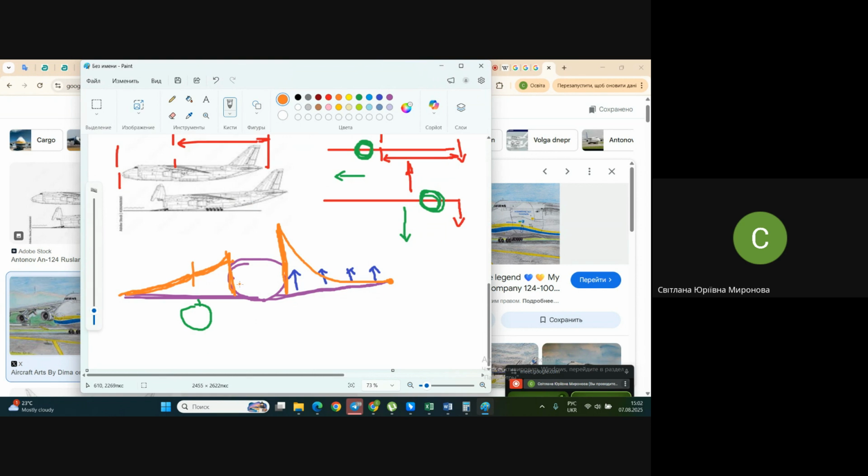And what will this result in, in terms of inner structure? It means that in this place you may use a less massive, lighter structure. So altogether, when you place the engine on the wing, the structure of the wing may be a bit lighter, less in weight. The same is true for the stabilizer. You do remember that the engine nacelle is on the wing, forgive me.